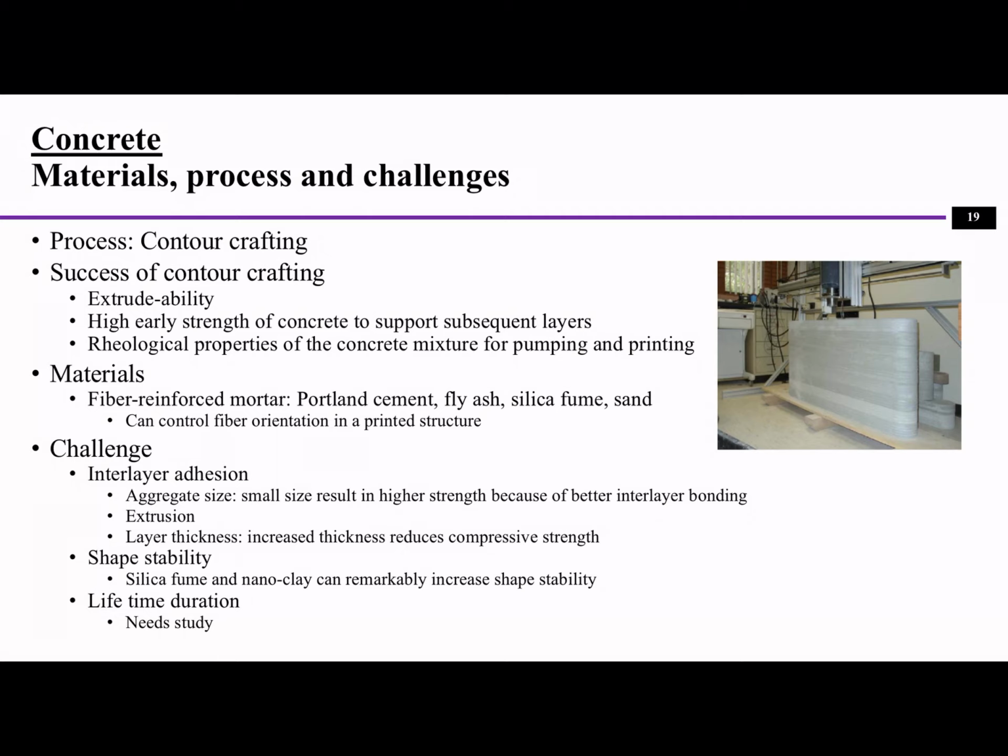It is similar to fused deposition modeling, so the factors affecting the quality of the process will be similar: whether the concrete paste can go through the nozzle freely, and rheological property issues for the mixture, the pumping and printing.